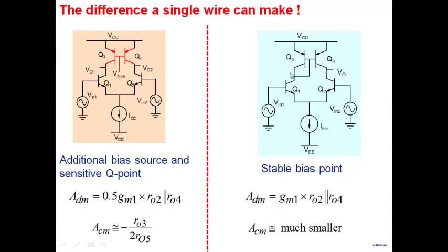And if we look at this particular amplifier, where we again have Q3 and Q4, but they're connected in this current mirror fashion here. So it's a current mirror load. And we saw that the bias points are stable. Both transistors are biased in active mode here. And the gain here is twice the gain of this particular part here. Although we don't have an expression, we showed through simulation that the common mode gain here, for one particular design, was close to 1 and the gain here was 1 by 100 here. So this has all the advantages with respect to this particular one.